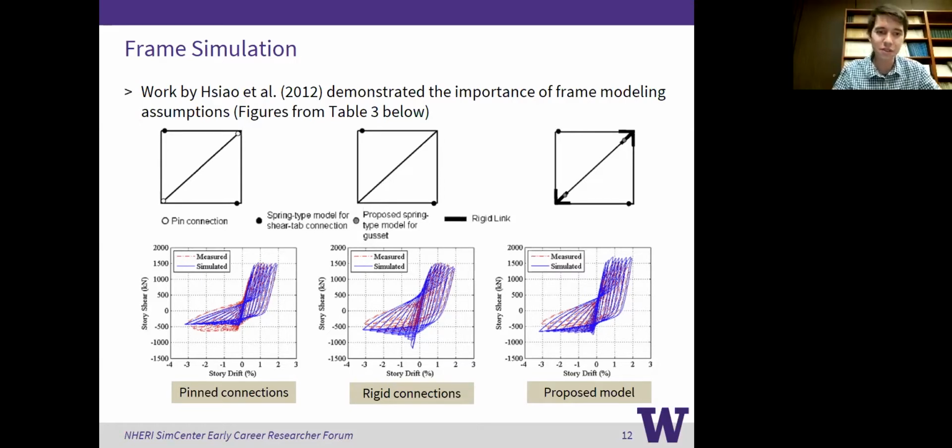And you want to make sure that you're multiplying the stiffness from the base case to a relatively large number, but not too large, so as to cause convergence issues. So I think even if you multiply the stiffness of the element by a factor of 100, that's plenty to model it as rigid.